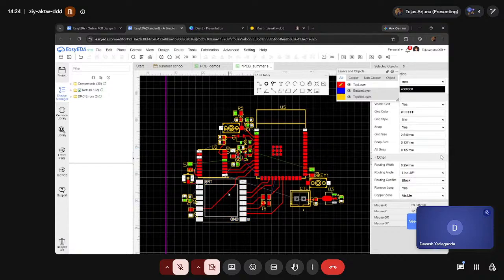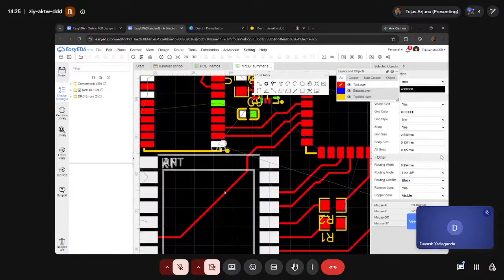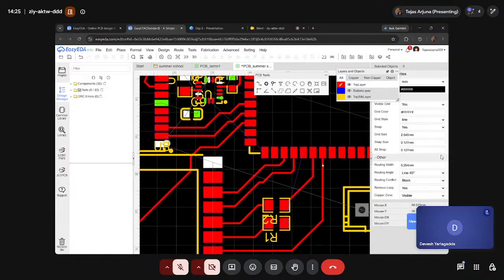The thing is, the traces, the radiated EMI is when the signal gets transmitted like EM waves to other signals or traces. This can happen when we have antenna-like structures. So if you have long traces comparable to the wavelength of the RF range, RF is radio frequency range.